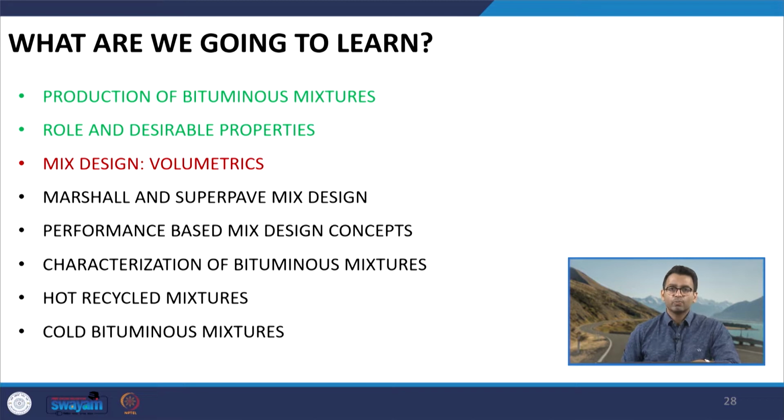So, today will be the last presentation on the volumetrics concept, and then further we will start talking about the two different mix design processes, that is Marshall mix design and Superpave mix design, and further we will also look at different concepts related to the performance based mix design, which is presently becoming popular and is being adopted by various highway agencies.